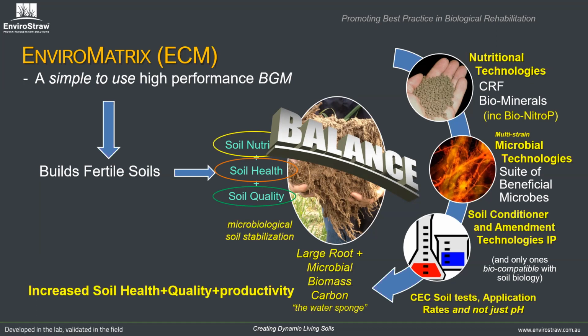So depending on obviously the climatic conditions, the soil profile and so on, we're looking at between 5 tonnes per hectare to 10 tonnes, depending on the profile. And again, we use the soil testing, soil analysis to work out what nutrients are required within the system, and then we apply at specific rates. So typical to most other hydromulch systems.